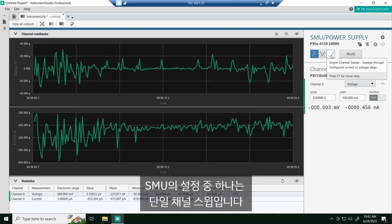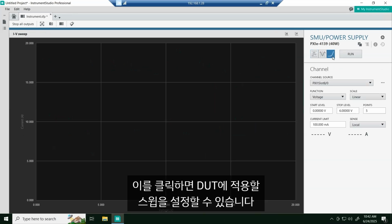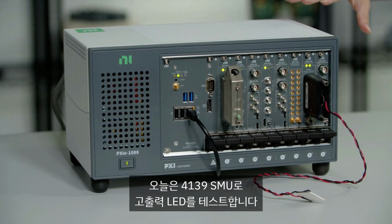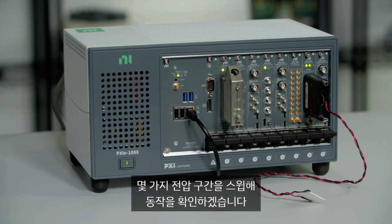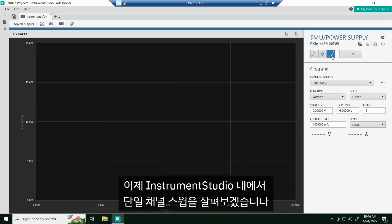One of the settings on the SMUs is a single channel sweep. So we'll go ahead and click on that, and this is going to give us the ability to set the sweep that we want across our different DUTs. So today in our system, I'm using a 4139 that is going to be testing a high power LED. And I just want to sweep across a few different voltages to see what it looks like. So let's take a look at the single channel sweep within InstrumentStudio.